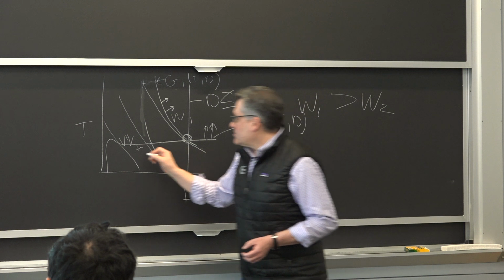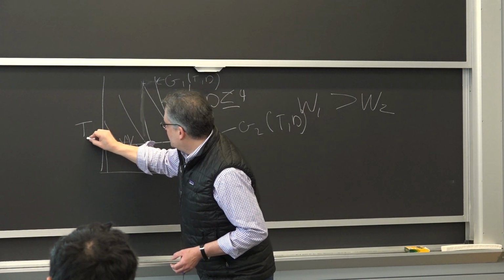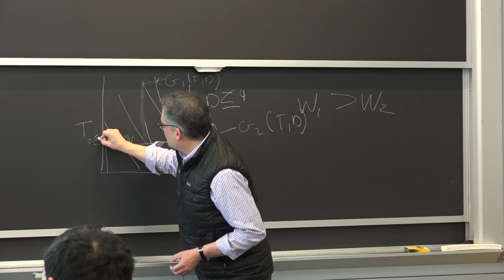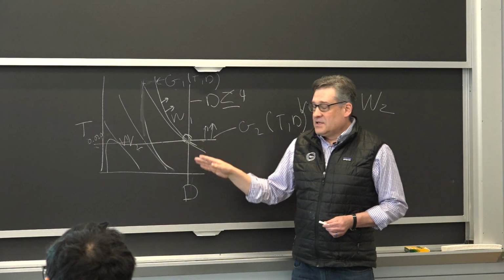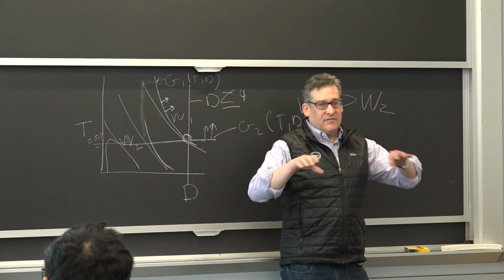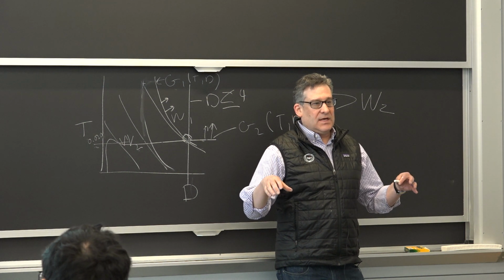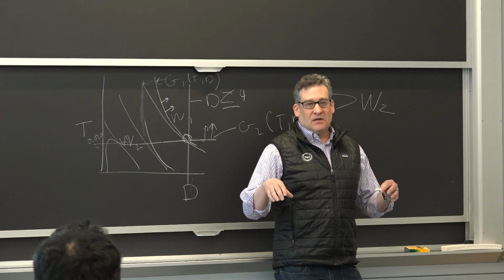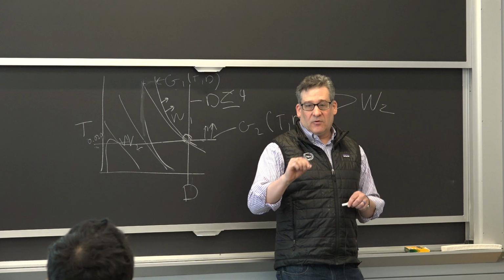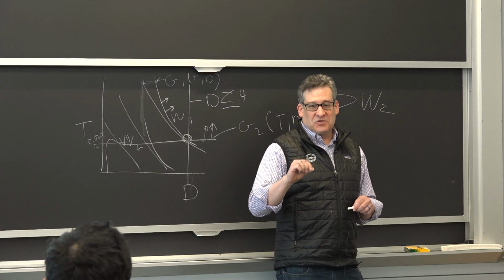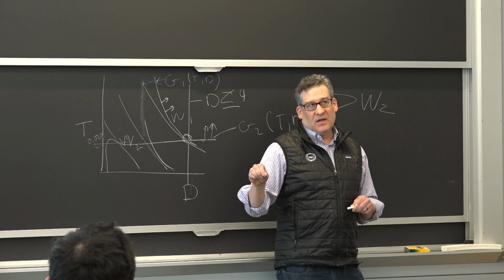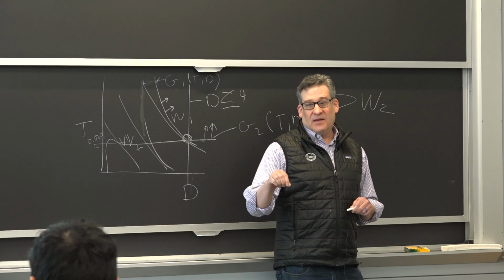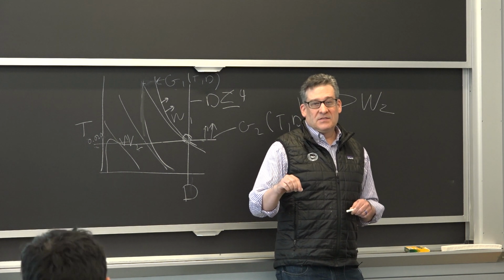And by the way, there's one other constraint I didn't draw on here. There's a T equal to 0.02 inches, so 20,000ths of an inch, right here. Okay, so remember we talked last week about that idea of having these tubes that are under bending and you could get the same stiffness at a lower weight by going bigger in diameter and thinner wall. Remember we showed the two bicycle frames, the green frame and the white frame, and the white frame was lighter than the green frame even though it was stiffer. This is what we're dealing with here.